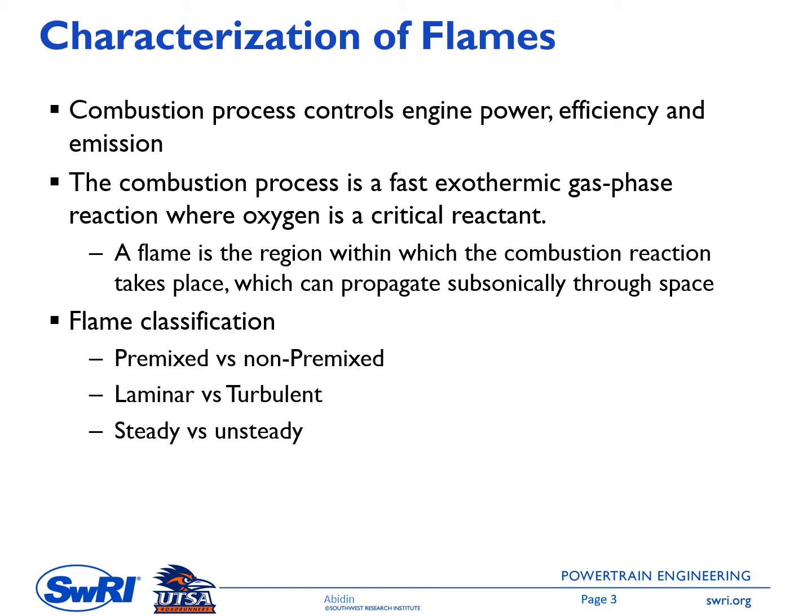In this case, the bulk flow motion of the mixture enhances the combustion process, on top of the laminar combustion process. And this bulk flow is represented by the average flow plus the fluctuation flow, and usually we use the parameter of turbulent kinetic energy to represent this fluctuation flow.